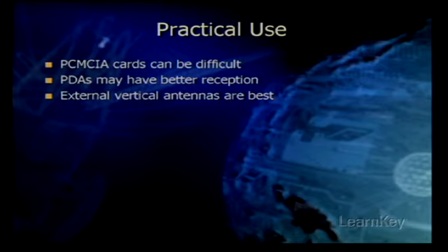And that's a lot of times why we will see, with a dual dipole antenna access point, one antenna being used in a diverse fashion pointing straight up, and the other antenna being pointed horizontally to provide a mixture of signals for different types of devices.